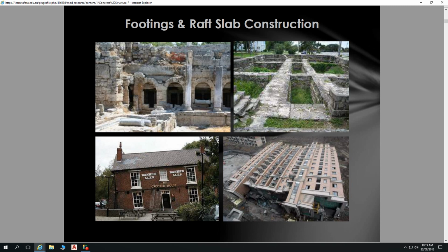Also, with our concrete, we'll want to use some of these things to ensure that our steel sits in the right place. They're bar chairs, formulated to make sure the bars have the right clearance from the base, because we can't have steel right at the bottom of our slab. As I said, moisture comes into concrete, and bars sitting right at the base have a chance of being subject to more moisture.